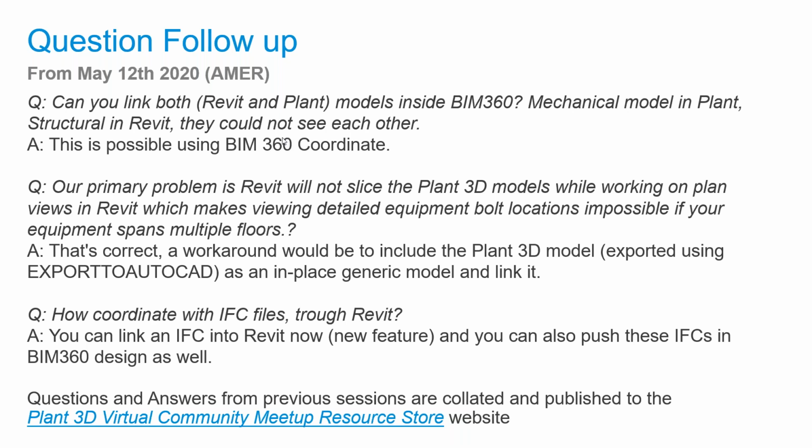Another question that came through last month was their problem in Revit was it doesn't slice the Plant 3D models while working in plan views. And so this mentions again why you need to do that export to AutoCAD command and then use an in-place generic model to link it in.